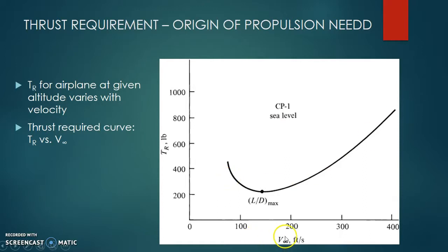What happens then? As velocity increases, even though lift is increasing, you don't need that much lift because your weight is not so much required to be balanced. So the excess lift causes it to go into a circular path, or to ensure that it doesn't go into a circular path, you have to adjust using your flaps and your ailerons. Therefore, that additional lift because of these high velocities is not very optimally useful. But drag is always a penalizing guy. No matter what you do with lift, it says, boss, my job is to penalize you. With additional velocities, in the regimes of higher velocities, drag increases. Hence, to match it, the thrust required keeps increasing.